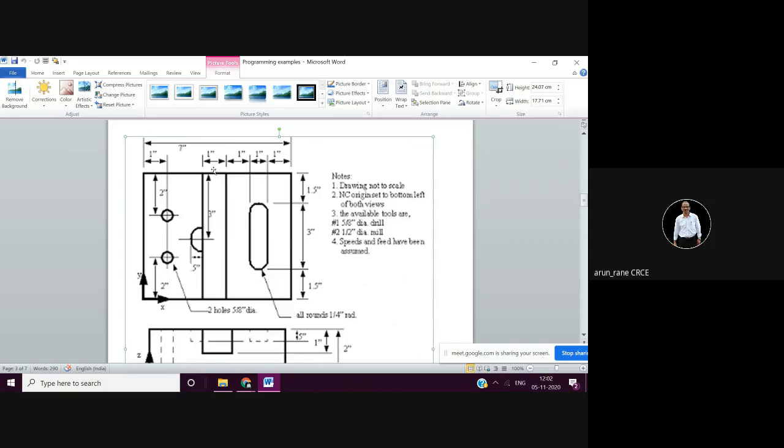So in order to cover that line, because you are moving the distance exactly by the diameter, you have to move the distance by 80% of the diameter and not exactly by the diameter. So if you are using a half inch cutter and you want to cut this 1 inch, then you'll have to take three passes. Two passes will not be enough. Yes, if you go for a 5/8 dia milling cutter, then you can do it in two passes. But